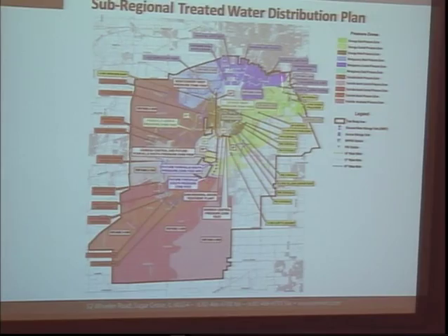So we did this exhibit to try to find zones that were similar in hydraulics so we could minimize the number of pumping galleries needed at the water treatment plant, and we think that it can be accomplished with 2 separate pumping galleries. Here's the centralized water treatment plant at Orchard and the Fox River. One line would come north up Orchard Road. That's our suggested, most direct route to get to the Village of Montgomery system, connecting in along Orchard Road. And that would be the red pumping gallery.